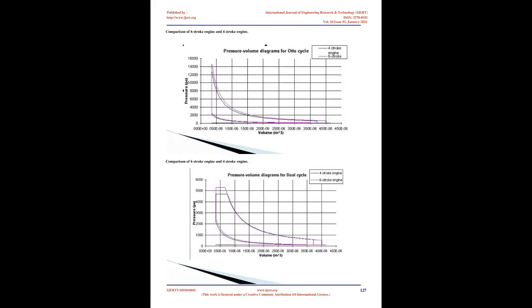Third stroke, first power stroke. The combustion chamber valve, 3, opens and the gases of combustion enter the cylinder, 5. This pushes the piston downward and hence is known as the power stroke. The crankshaft rotates for a half cycle. It should be noted that the air in the heating chamber is continuously heated and this results in a further increase of pressure. Fourth stroke, exhaust stroke. The exhaust valve, 4, opens. The piston moves upwards and the exhaust gases are removed via this valve. The crankshaft rotates another half cycle.